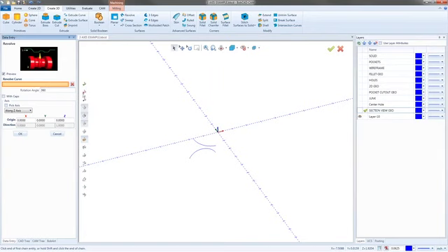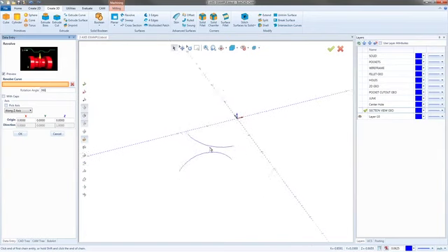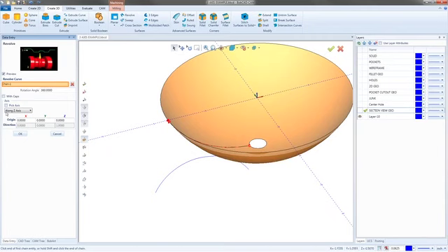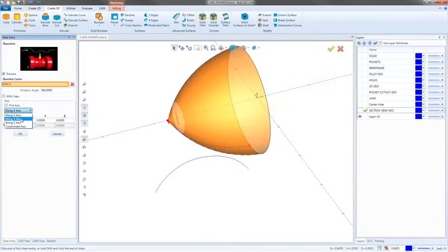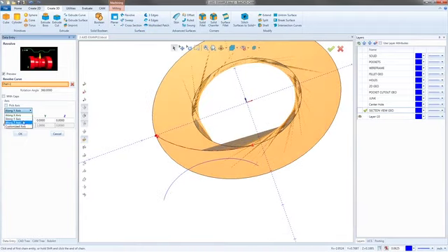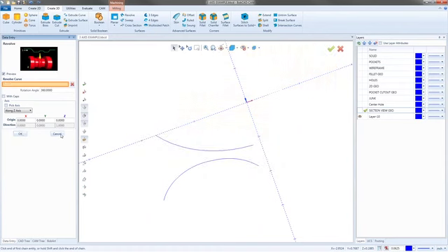And pick your geometry. The geometry I want first is this line here. Now this is a single entity. There's really no right or wrong direction for this. So all I'm going to do is find my midpoint and then go either to the left or the right. Doesn't matter. Click it once, hold shift, click it again. There is the shape. We want to make sure we're going around the z-axis. So we're rotating around that z-axis. There's the arrow, the blue one right there. So we're spinning around that. If we were to go around an x-axis, it would look like that. If we were going along the y, it would look like that. So we're going to go along the z and then just hit OK and cancel out.